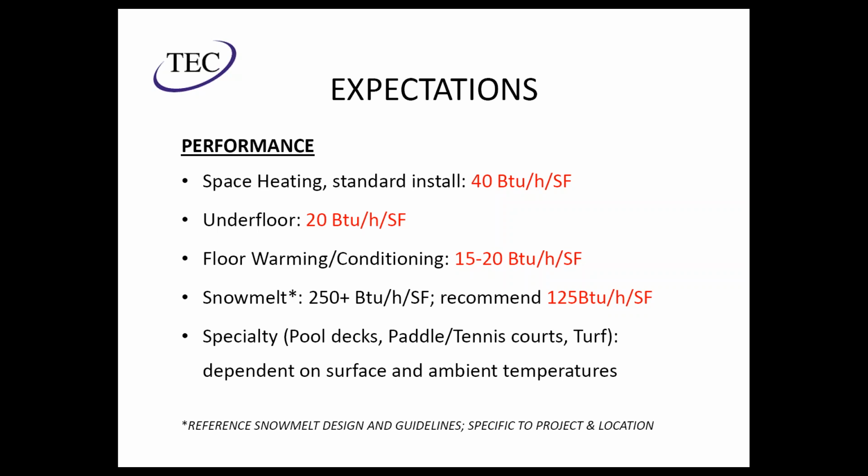It's by code so that the surface temperature is not objectionable to the patrons. So using standard room temperature, the most you can really extract from a standard concrete floor with a minimal floor covering is around 40 BTUs per square foot. Now that varies. It can get a little higher or lower, but it's a good estimate for what you can expect to extract from a space.